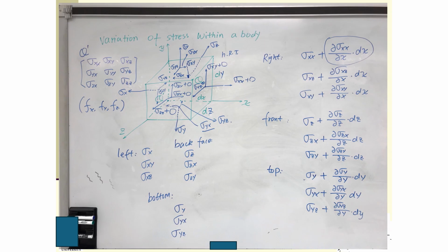And this guy's stress state is sigma xx, sigma yy, and sigma zz. Please note that here all the shear stress and normal stress, I use sigma to denote them. However, as I said, we have two subscripts. If these two subscripts are different, it means that this guy is shear stress. If these two subscripts are the same, that means this guy is a normal stress, and you need to know this convention very, very clearly. Keep this convention in mind.